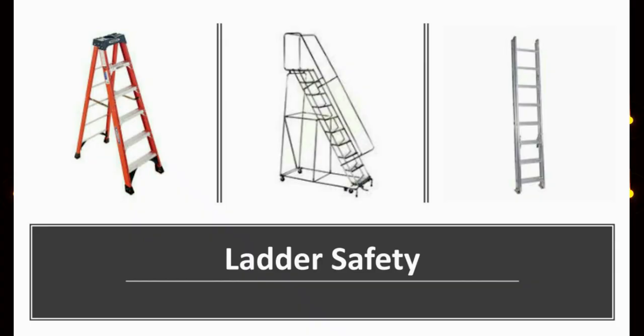You see some illustrations here of types of ladders. On the left there is a portable ladder, a good heavy-duty fiberglass ladder. Then in the center is a safety angled rolling ladder that you commonly see in commercial places like Home Depot, Menards, etc. And then over to the right is an extension ladder. I'd call your attention to the fact that that's an aluminum extension ladder and likely to have maybe a 250-pound weight limit. That's both the person climbing and anything you happen to be carrying with you too, so keep that in mind.